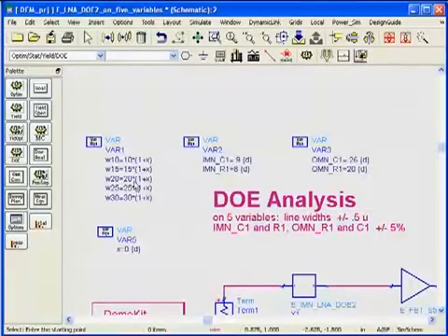My 5th variable is the width of the lines. I can choose different widths as each one, the 10 micron, the 15 micron, the 20 micron, the 25, 30 micron. I can choose them as separate variables, and I can run many more experiments. But I decided in this experiment to put all the width of the line in the design as one. They move up and down together. So what I did is I multiply each of the 10 micron, 15 micron, 20 micron, 25, and 30 micron by a factor 1 plus x.